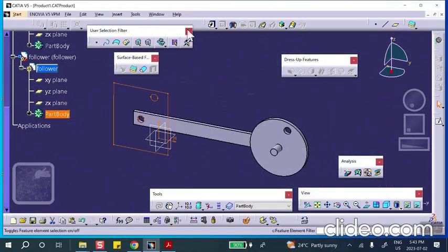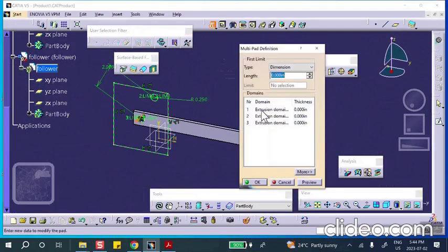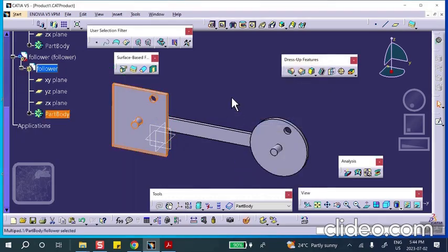Once again, I'm going to do a multipath to make my job easier. This is going to be the big thing, the big square here, so I'll make it padded by 0.25. This is going to be the hole here. I'll leave it as a hole. And this one is going to be the shaft. So I think I made it 1. I'll make the same thing here. There we are. Okay, of course, I'm going to turn this thing around and stick it in that hole.